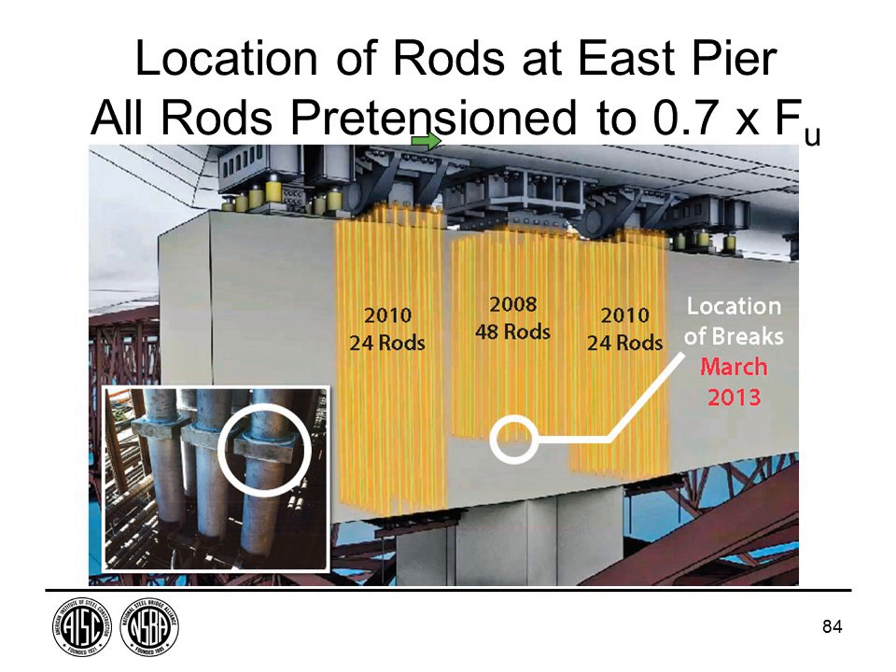After they got everything in place, then they could lower it down onto the piers. Before they lowered it down, they had to place these between the bridge deck and the pier cap. This is a bearing. These are shear keys. So there was no way to stick these rods in from the top. Normally the rods are continuous all the way through and you could just push them up through and tighten them. But these couldn't, so they stored these in the pier cap while they were building the bridge.